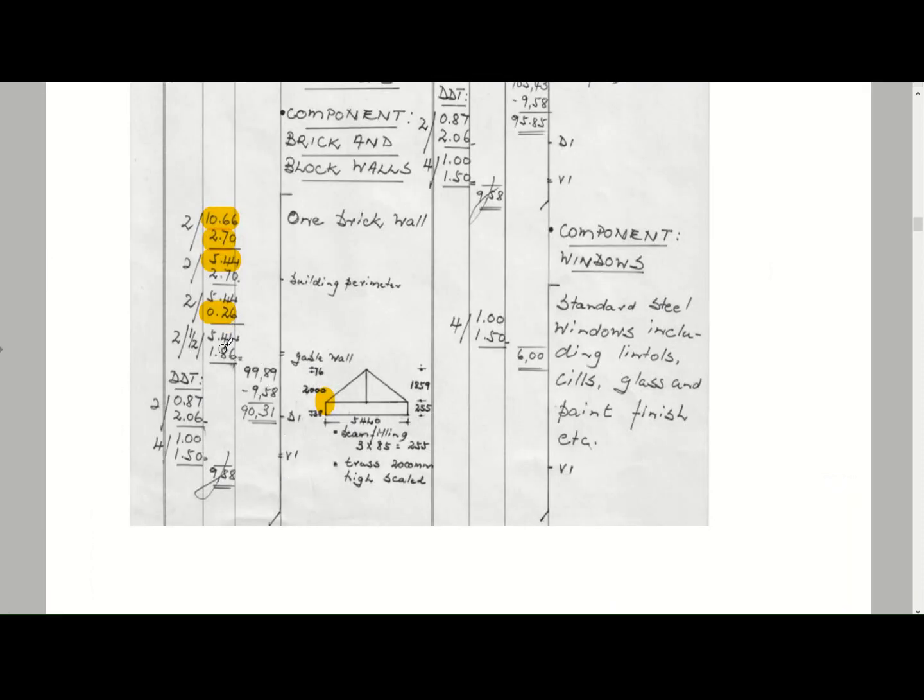So that is how they did that. And then here's the calculation for the gable end. You will see there are two little stripes, and there's the description for your gable end or gable wall, and they calculated that the height of your gable wall is 1.86 meters. Your formula is half of your height times 5.44, and you've got two of them on either side.